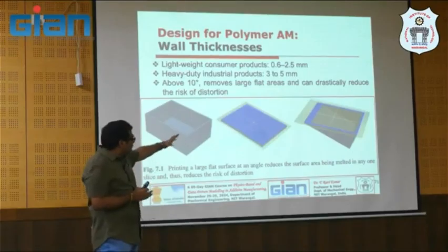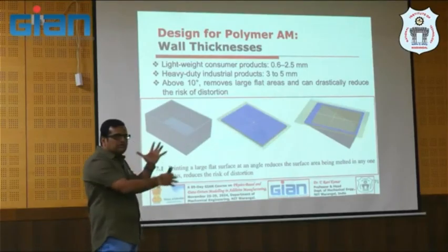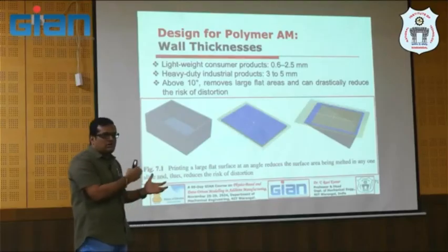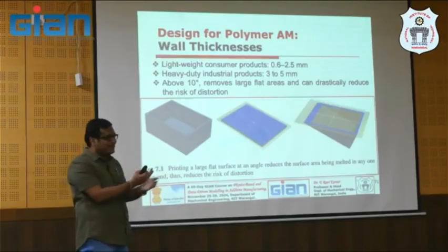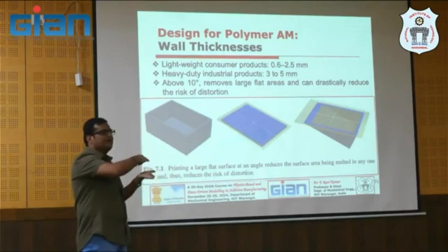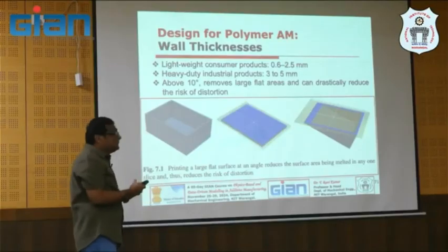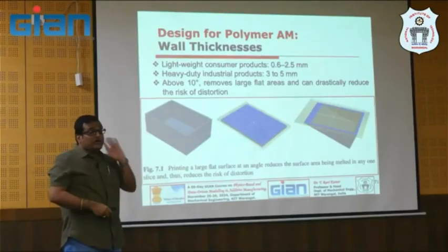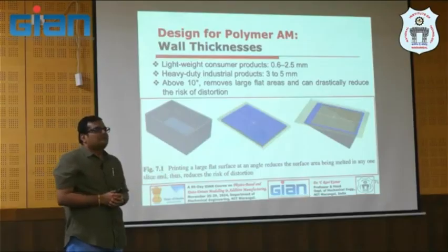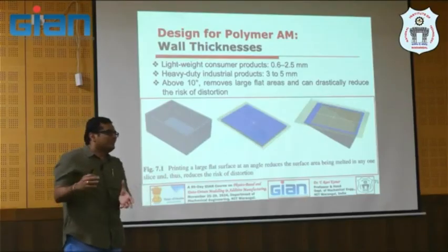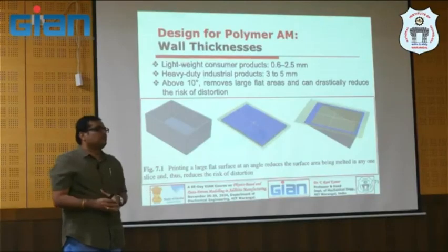You are not allowing such kind of residual stress in a single layer, and you are distributing it, if you make it a 10-degree angle, into a number of layers, not in a single layer, right? So in that way, we need to come out from the conventional mindset to the additive mindset.